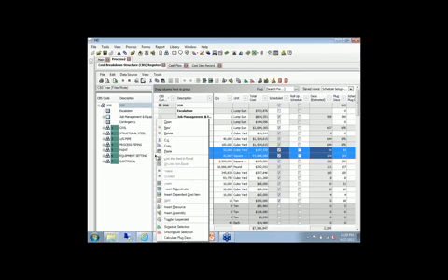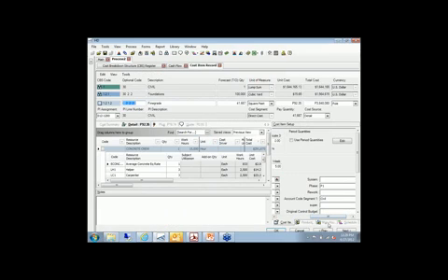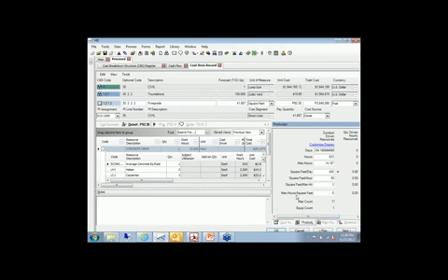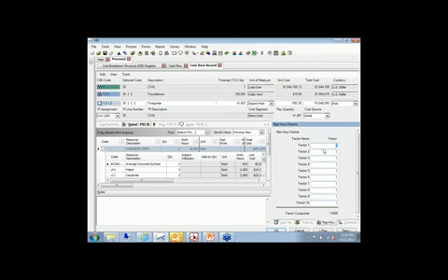Right, so I'm going to highlight those two items, and this is a typical use case in hard dollar. I'm going to open those up. And what we're going to do is apply a factor. If we look at the productivity assumptions, you can see that we were planning on doing for the fine grading 400 square feet per day. Maybe we want to apply a factor here. Maybe we're going to need twice as many man hours per day. So I'm just going to apply